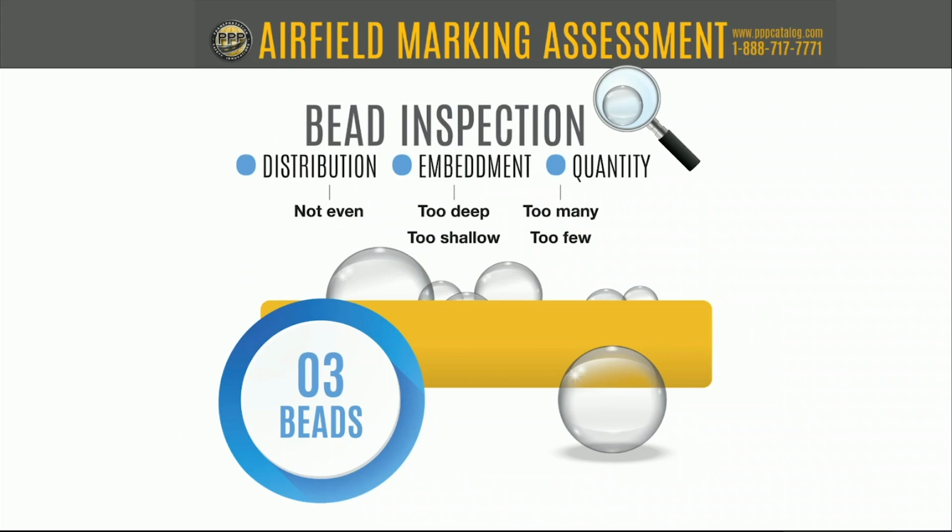Greg mentioned that yellows can appear white at night with poor embedment or when the beads sit too high up in the paint. That is exactly why, in my opinion, the FAA no longer allows us to use type 3 glass in red and pink paints. It is an application issue. It is not necessarily a material issue. I know this from experience. I've seen really good applications that look beautiful and perfectly red at night and perfectly pink and do not wash out the inscription. I have pictures of it when we do our symposiums. I get up on my soapbox and go on and on about it, but I'll spare you today.